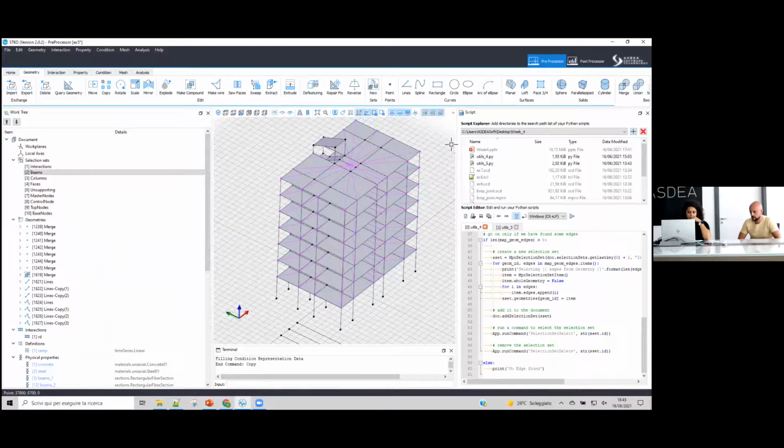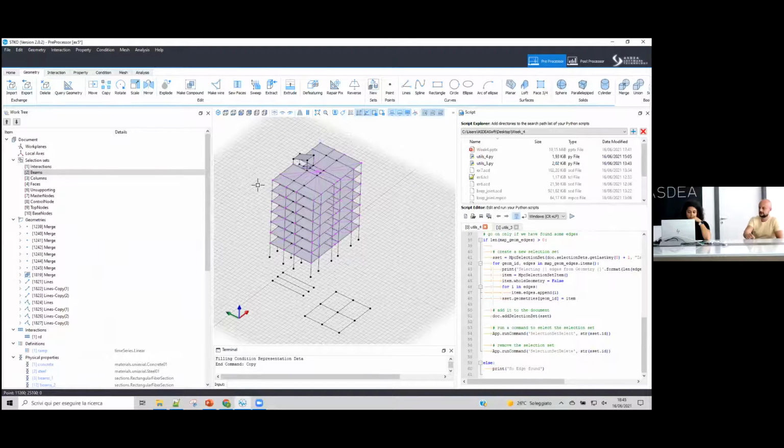Yeah, actually you have to understand why you had all those copies overlapping. Probably you clicked on the copy command and then you started clicking on the same point over and over again. Or sometimes it happens because people want to perform a parametric copy. So you can move your object and start typing the distance, okay? But every time you type the distance, you have to type an increment. Otherwise, you will copy many times on the same location.